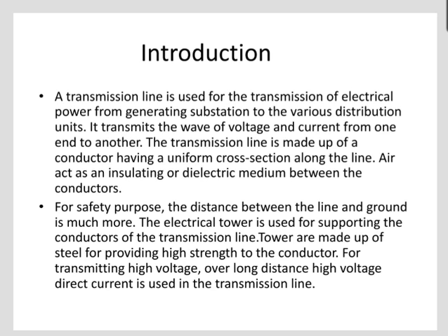So, for very low frequency, transmission line effects are negligible. For medium frequency, only very long cables require special consideration. However, at 1 GHz, many PCB traces must be treated as a transmission line, and as the frequency climbs into the tens of GHz, transmission lines become ubiquitous.